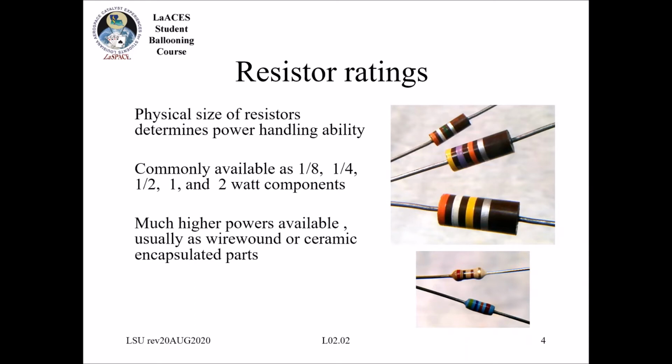They can get very hot. So, commonly available is 1/8 watt or 1/4 watt or 1/2 watt, 1 and 2 watts. And then there's also much higher powers available. Just depends on the need. So just take a look at that. And then this will also change significantly with the surface mount resistors that we were talking about. So be very aware of this.